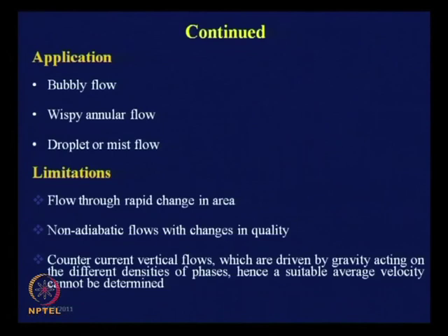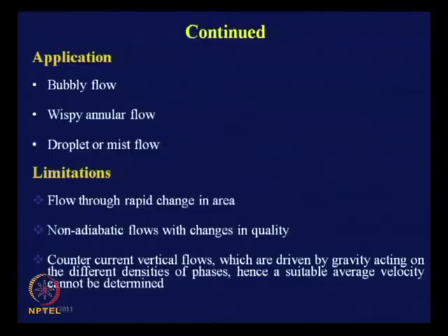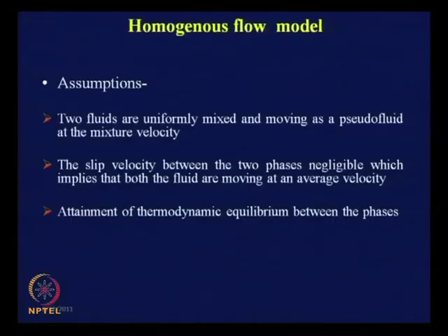Under these situations, there is rapid acceleration, rapid pressure changes, and we cannot use it. Then suppose we have non-adiabatic flows with changes in quality. The moment all these rapid changes in quality, rapid change in pressure etc. take place, thermodynamic equilibrium, the last assumption which I had shown in the previous slide, if you remember, is no longer valid.